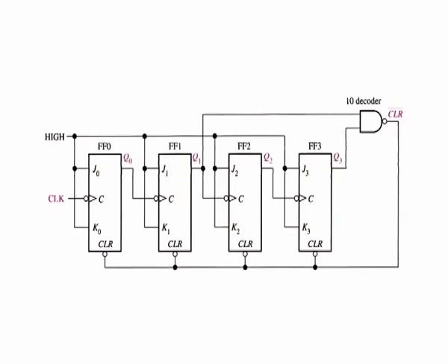When the counter goes into count 10, the decoding gate output goes low and asynchronously resets all the flip-flops. The resulting timing diagram is shown in the figure.